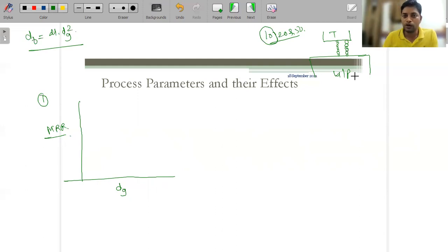Okay, why is it important, guys? Because the vibration which is transferred to the tool is in the range of 15 to 50 microns only. This is also in a very small range. This is exactly the vibration which is really required at the workpiece surface.